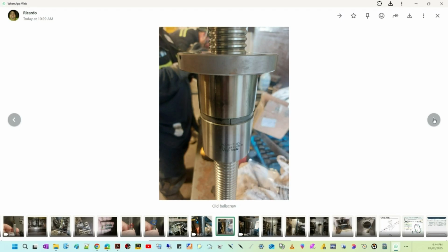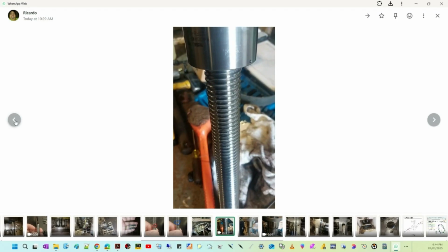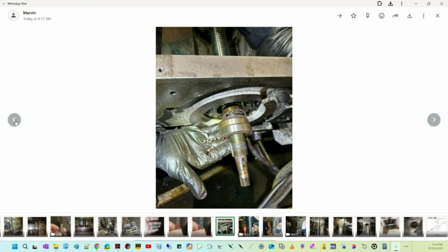Precisely. So you get this huge position error building up very quickly. The commanded position races ahead, while the actual physical position lags way behind because the screw is binding up. Once that error exceeds the preset limit, the MCS DIFF alarm triggers. Bang. The alarm triggers to stop everything before more damage occurs. So yeah, that failed bearing cage was absolutely the root cause of that specific alarm sequence.